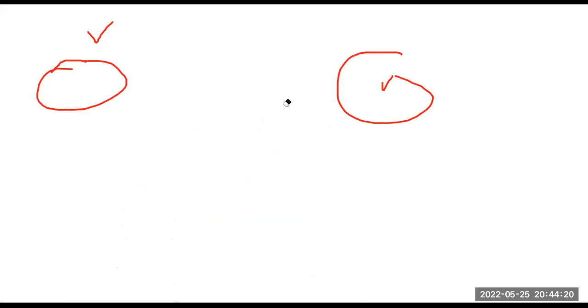You can choose something like temperature and say one of your deviations is reverse, right? What is reverse temperature? You know, with your analysis, it can only be high or low, for example.